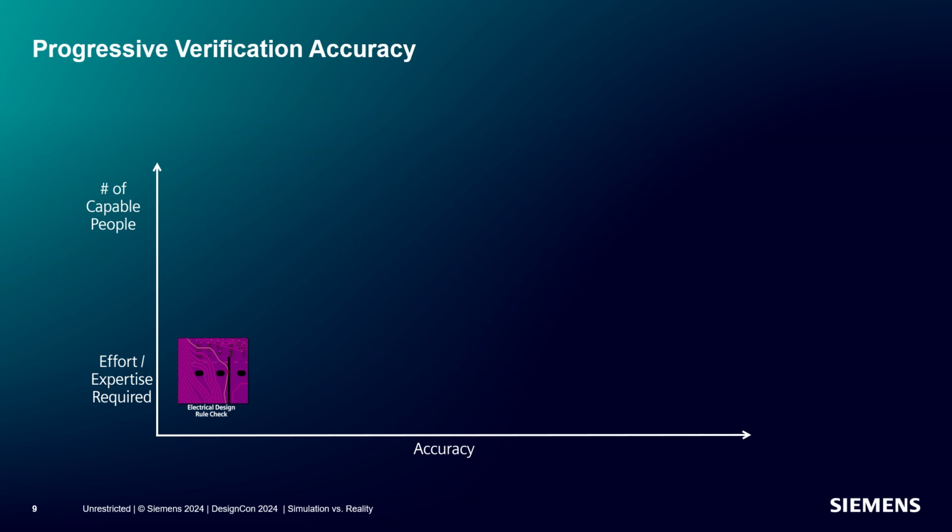The majority of issues flagged through DRC are going to be immediately obvious to the designer. You'll look at it and it'll either be obviously an issue or it will obviously be fine. And as things are flagged, you'll be able to sort them like this. It'll be pass, fail. There will be ones that skirt the line that will be of concern here. Something you look at that you say, oh, I don't know if that's going to pass or fail. And those are the ones that will continue on in the process.